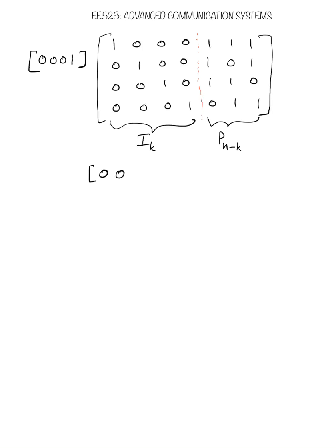And just to speed up things, if you notice, this is the identity matrix, right? The first part of the generator matrix is an identity matrix. And identity matrix means like the number 1, right? If you multiply anything with the number 1, 4 into 1 is 4, x into 1 is x. So if you multiply this vector with this matrix, you will get the same thing. So the first 4 bits are always going to be the same as the message bits. So henceforth, when I do subsequent examples, you need not calculate the first 4 bits directly because this is an identity matrix.